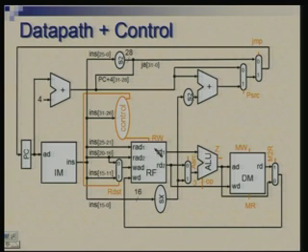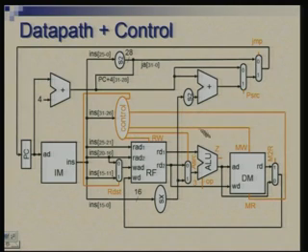Whether we have to write register file or not can be determined from this. ALU source can be selected, it can be determined from this. Memory write and memory read. So, if it is load instruction, we will do memory read. If it is store instruction, we will do memory write. Then control of this multiplexer. It has to distinguish between load from other instructions. So, that also can be done.